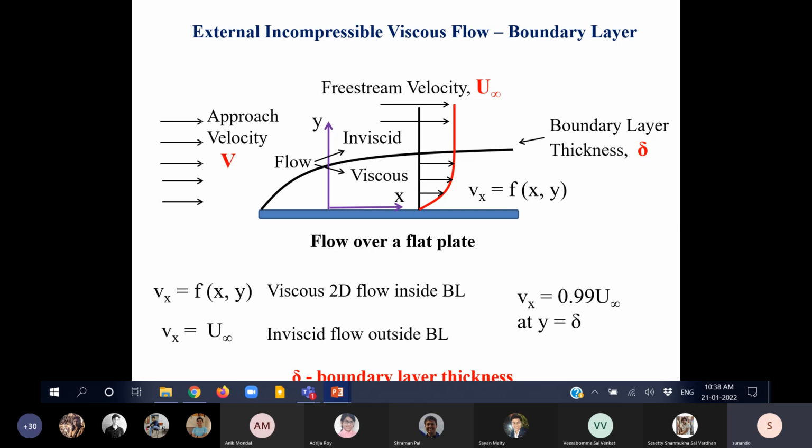They knew at that time that there is something called drag force, but the evaluation of the drag force was almost impossible to achieve because the complete solution of the Navier-Stokes equation in such a large flow domain was impossible. So then came Prandtl and he revolutionized it by simply assuming that everything takes place within a layer very close to the surface. All the momentum transfer, drag, etc. are caused by the thin viscous layer, in which the viscous forces are important.